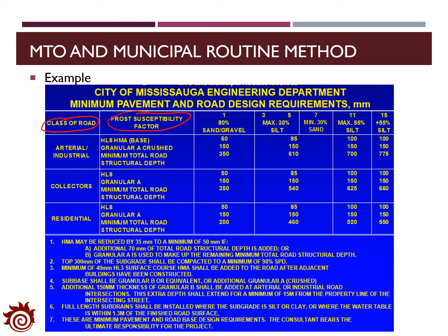Generally, in this city, the road is categorized into 3 types: arterial or industrial roads with heavy traffic, the collectors which will connect the arterial roads with the residential roads, and it has a median level traffic. The last one is the residential roads, which is inside the communities. The traffic there would be very low.